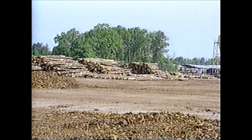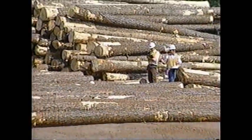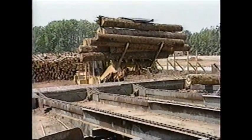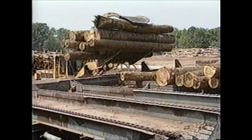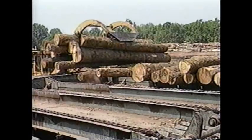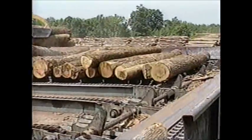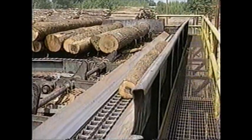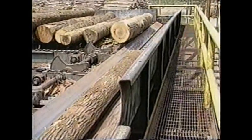Loads of logs are identified as to logging site or contractor, and scalers spot check incoming loads to ensure that plant standards for length, diameter, and log quality are being met. The plant utilizes better quality logs in order to maximize the yield of high-quality veneer. Logs are sorted at the logging site, with smaller and lower quality logs diverted to the production of other products based on wood fiber, such as oriented strand board. The logs on this deck and those being processed are yellow poplar, a Group 2 hardwood possessing good strength and stiffness qualities.